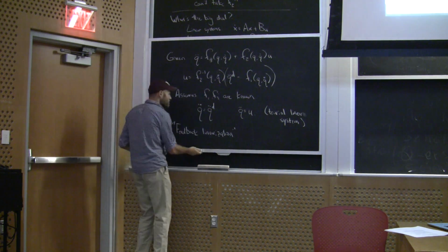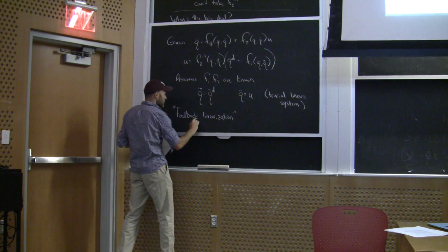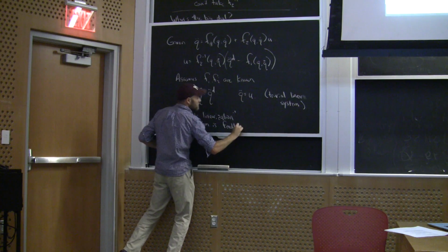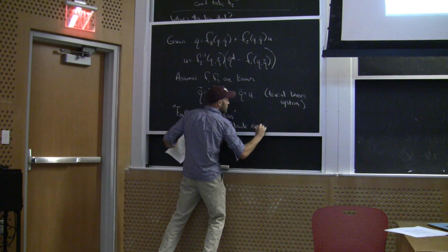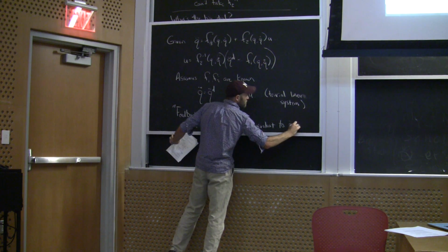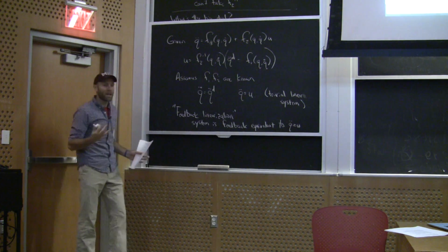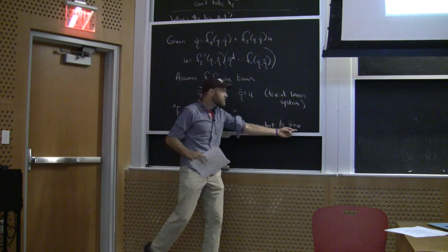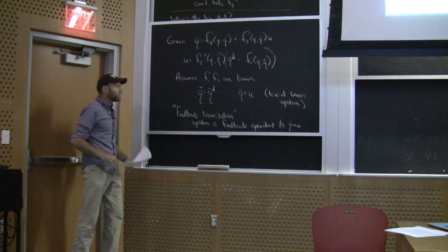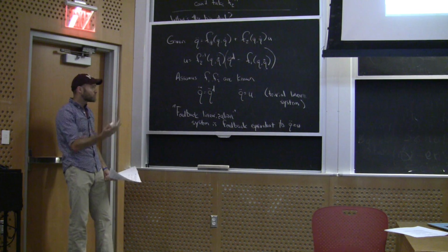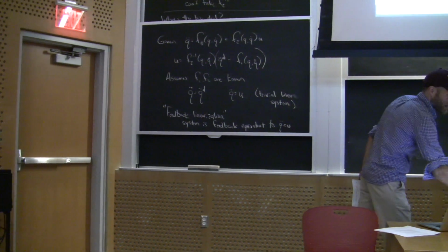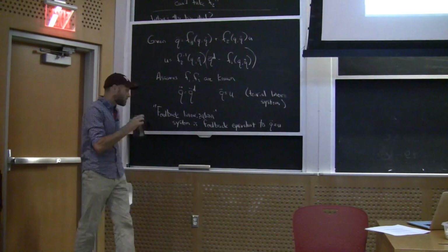Another way that people might say this is that the system is feedback equivalent to q double dot equals u. Right? Through a simple feedback law, I can change my dynamics into a dynamics like this, and I know everything about how to control that system. We can make it do whatever we want. It still can't follow arbitrary trajectories, right? It's still a second order system. But we know a lot about how to design that to do what we want.